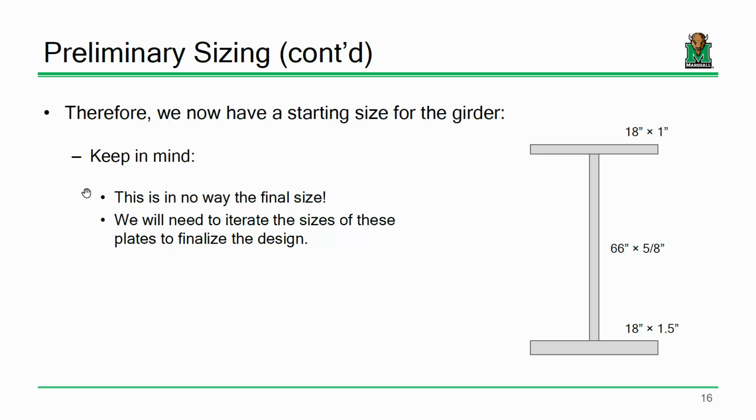I don't have an answer for that. But I'll say this. Your span lengths in this class, you all are going from the 60s to the 120s. Y'all might be in that range where a plate girder versus a rolled beam is sort of the dividing line. I'm not telling you, because you need to do some research on your own. Now keep in mind, we're talking about steel with concrete. You're just basically looking a lot of stuff up from standards. We're going to talk about some DOH standards later on. So, everybody good? All right.